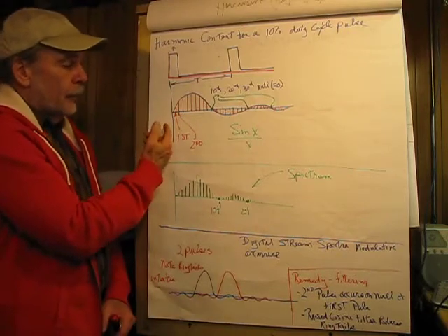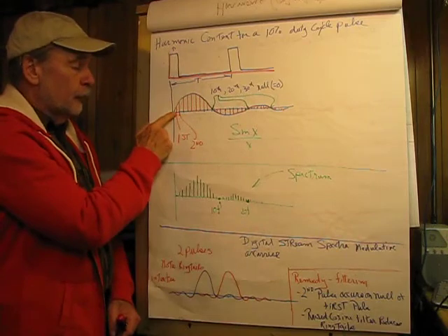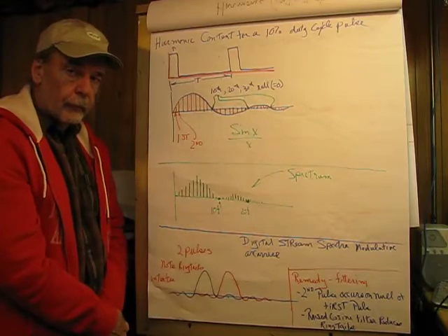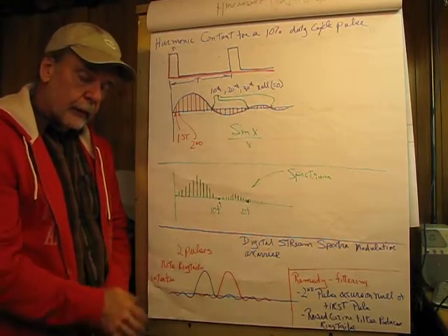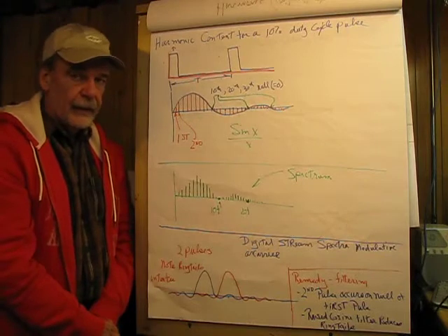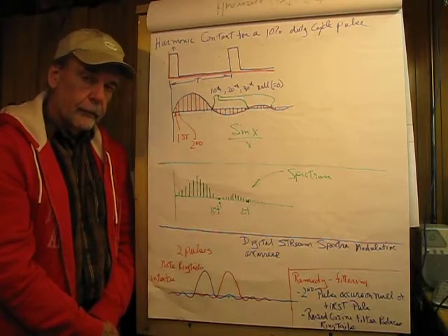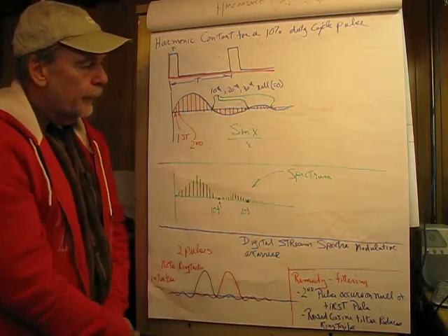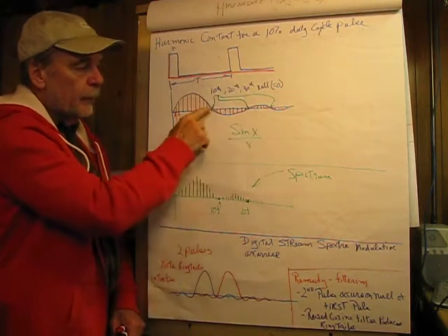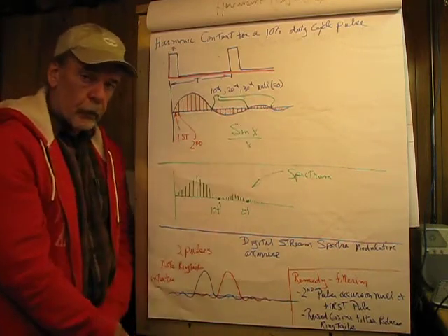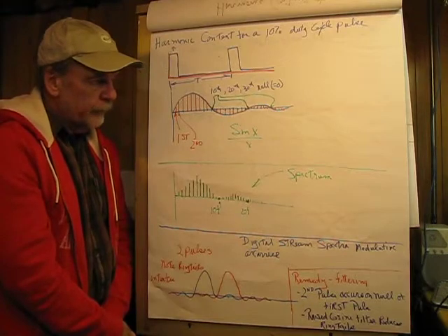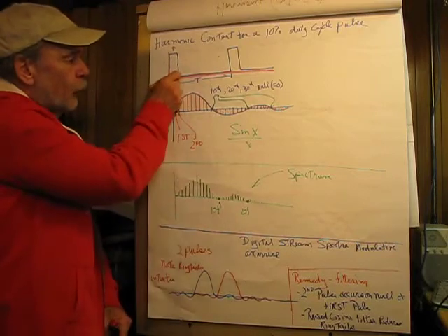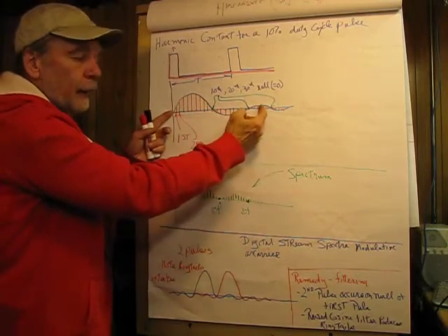And you can also see that we start with the first harmonic being relatively small and hit a peak, and then drop to 0 for our first lobe. Now what that's saying to us is that the first harmonic does not have to be the largest, as it is in the square wave. When we get over into here, this will produce a negative answer, and then positive answer, negative answer, and this ringtail here gets smaller and smaller in amplitude as frequency increases.